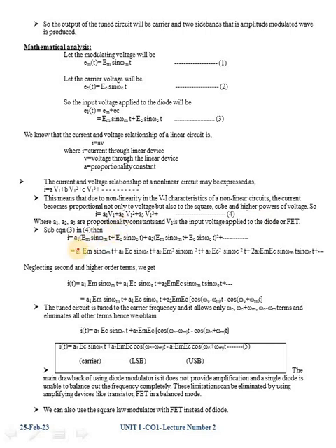So i = A1 times, what is our V1? Em sin omega mt plus Ec sin omega ct. Similarly A2 into the same input signal is considered. The only thing is, according to the square law principle, we square the second term, then cube, then apply the power of 4 and so on. Neglecting the higher order coefficients, the second order and higher order terms are eliminated in the above equation.